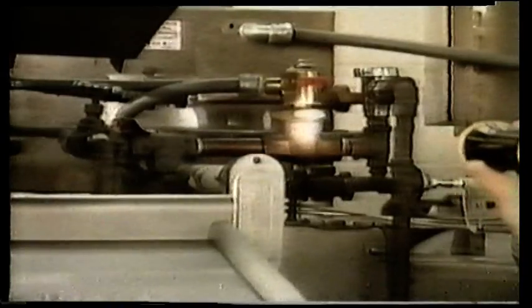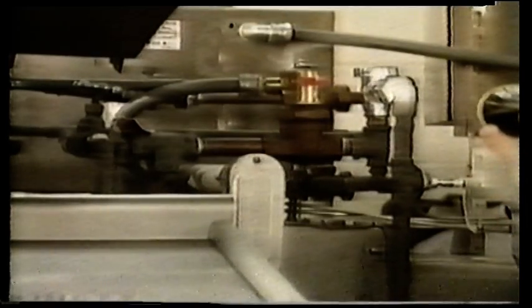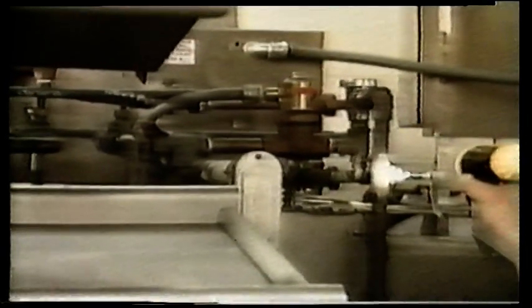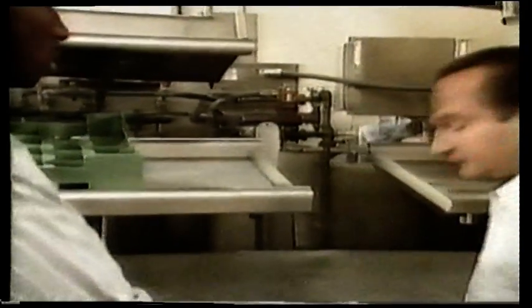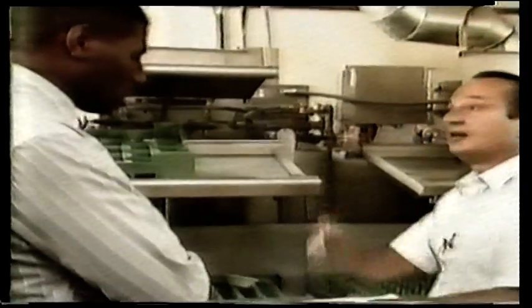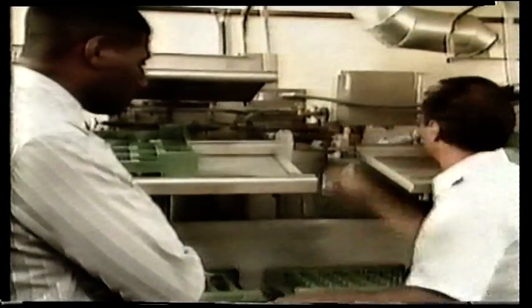Most large cafeterias and kitchens incorporate an automatic dishwasher utilizing soap injection. The survey team must look for atmospheric vacuum breakers and determine if the shutoff to the atmospheric vacuum breaker is located on the upstream side and the soap additives are injected below or downstream of the atmospheric vacuum breaker. The automatic dishwasher in the hospital had properly installed atmospheric vacuum breakers.